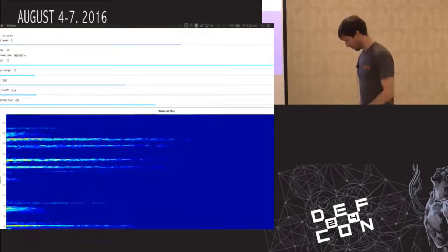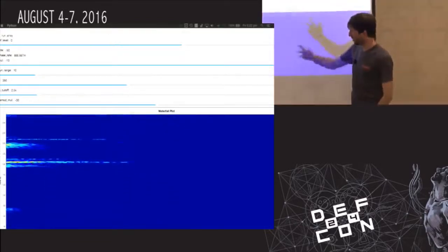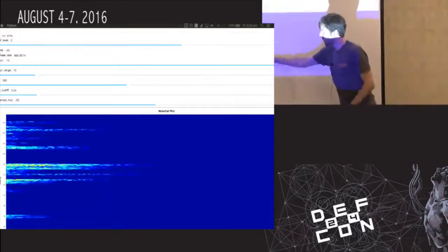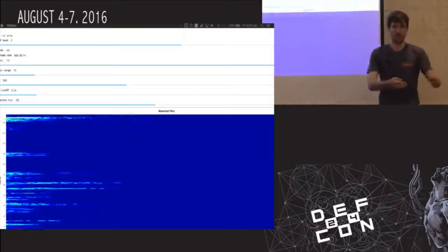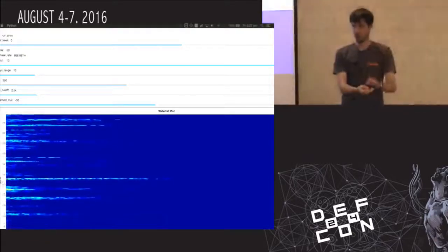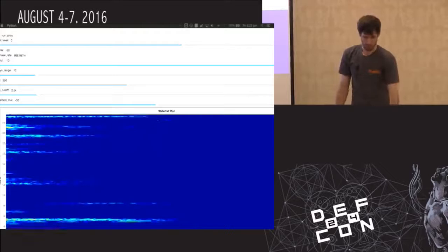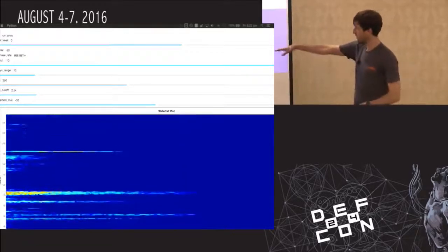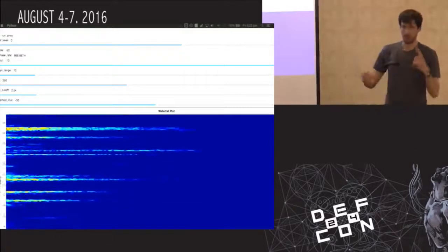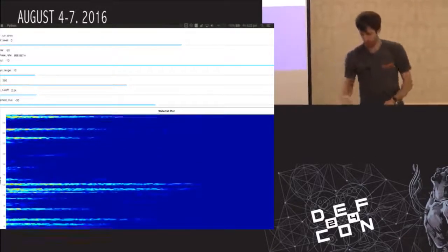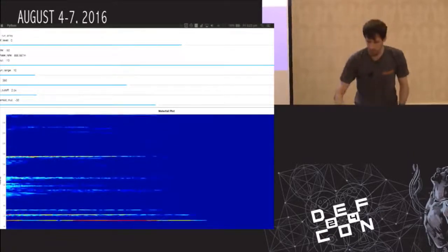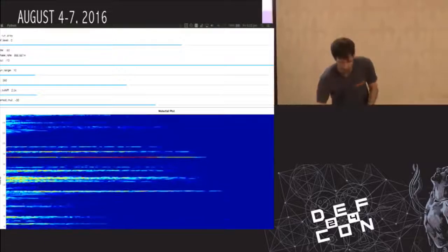And because that can go through that convolution, this is an FFT plot, but the bin that it falls into is actually directly related to the range information or the propagation of that chirp from one point to another one. And these signals that the microphone's picking up are quite noisy, so you get this kind of stuff. But in other systems, you can actually process and filter that out pretty effectively. One other thing is that this doesn't work very well because, again, this is just hardware speakers and a microphone.